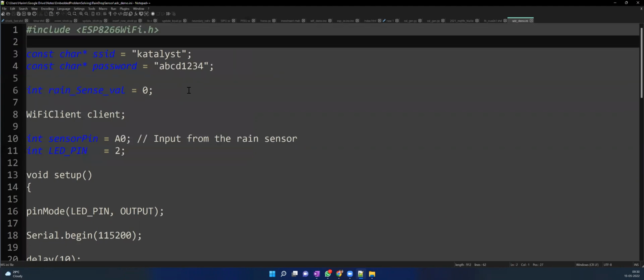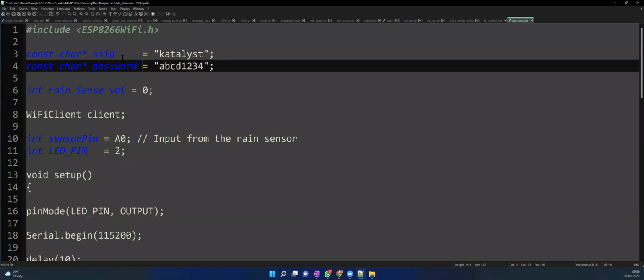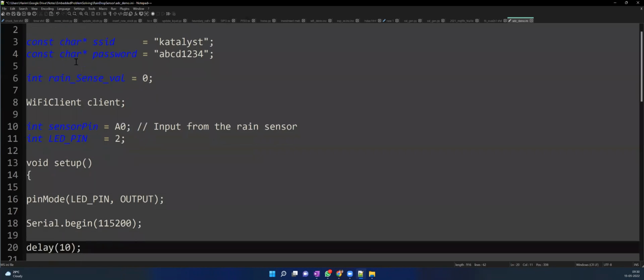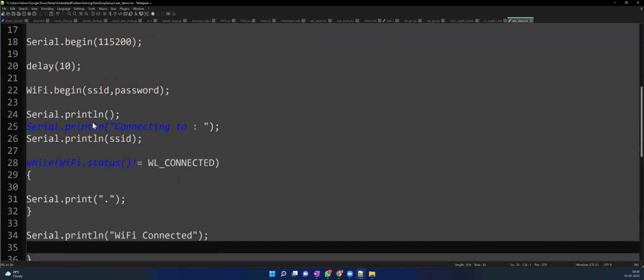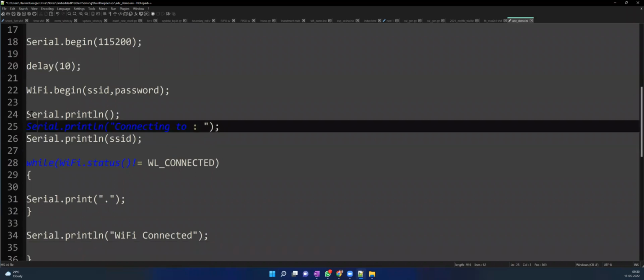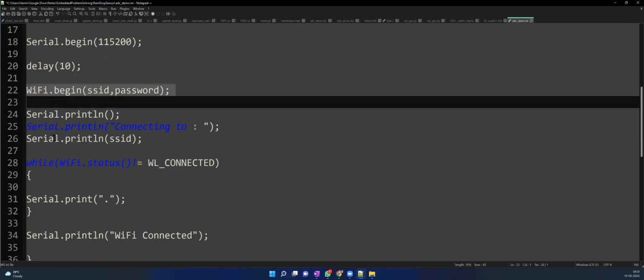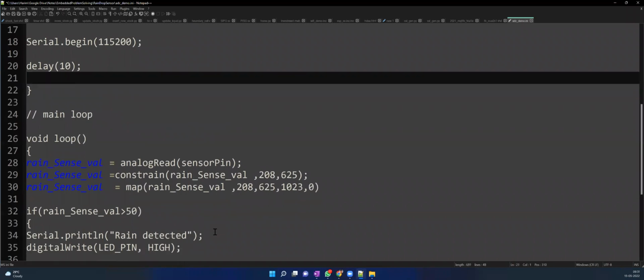#include WiFi, because we are using the ESP8266 Wi-Fi board, right? So let it be these parts. This also will not trouble us basically. So WiFiClient also let it be there. ADC sensor pin we have made it A0. So let it connect to Wi-Fi. No, let's disconnect Wi-Fi. Okay? So we'll not focus on this. So we'll just Serial.begin. We'll not use Wi-Fi now.